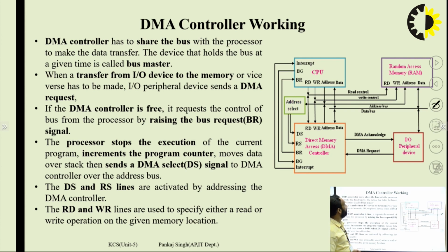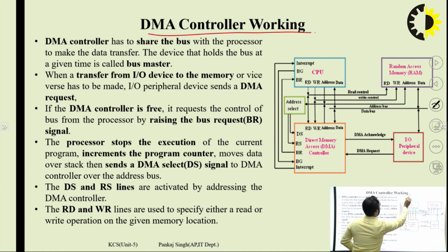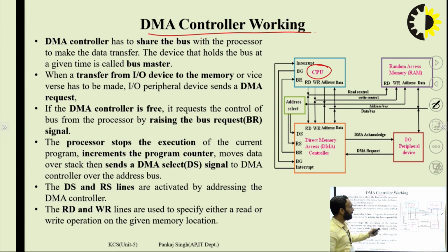Now, we have a detailed block diagram of this process on the slide. Hopefully, the slide is clear to all of you, and it explains the working of the DMA controller. It works as we see in the given diagram. All the operations that a CPU has, a DMA controller also has, like read, write, address line and data line. Likewise, a CPU has bus request, bus grant and interrupt input signals, and the DMA controller also has bus request, bus grant and interrupt.